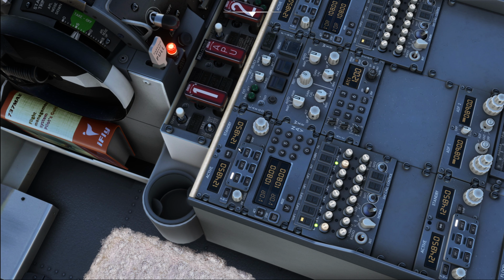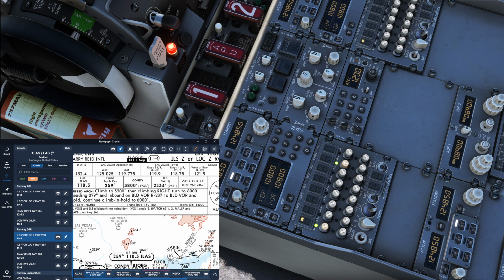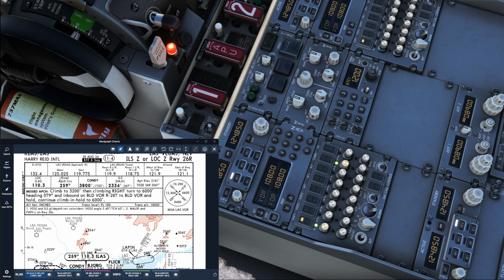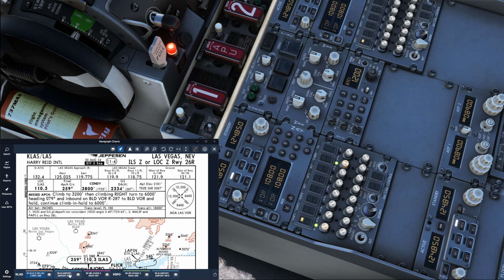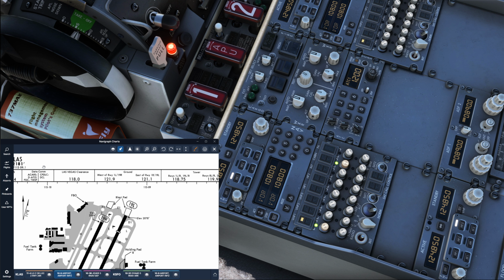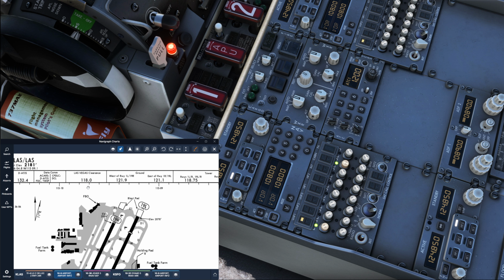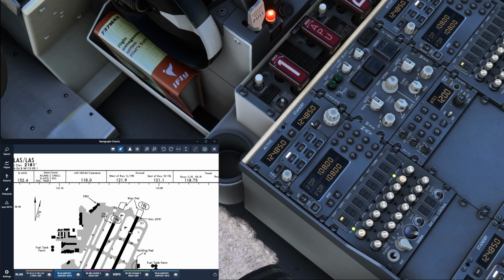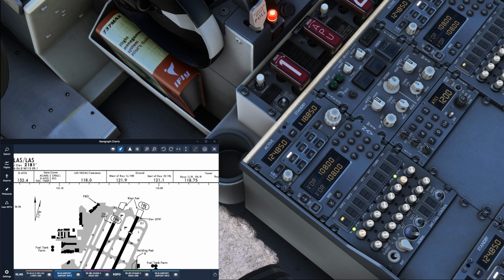Moving down to our radio, we are going to use radio number 1 for our active ATC communication, so that means we are going to tune whatever frequency is necessary. Now, if we were flying this one in the real world, then I would do my radio setup as follows. First of all, we will need the delivery frequency, so that's 118.0, as we can see up here. So I'm going to tune 118.0 into the active frequency, and then I would pre-select the ground frequency,